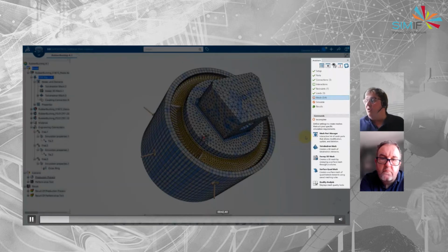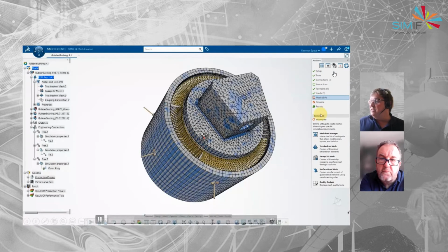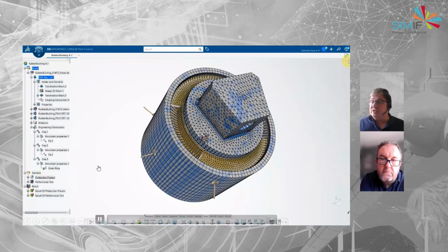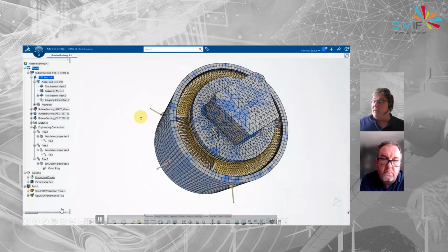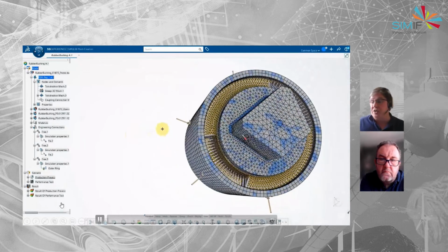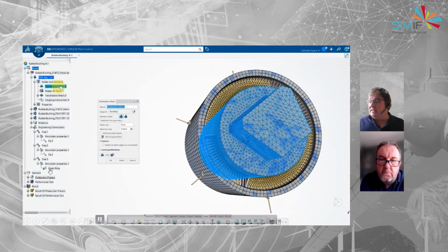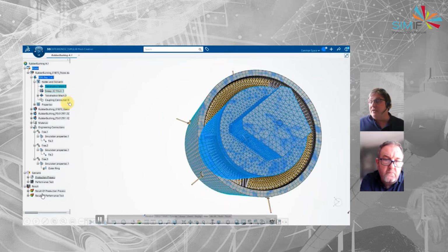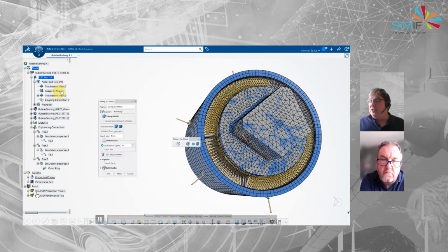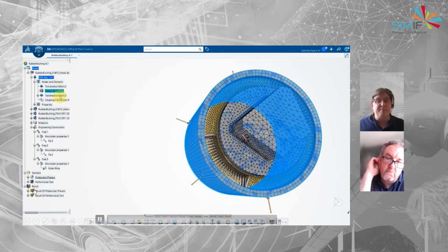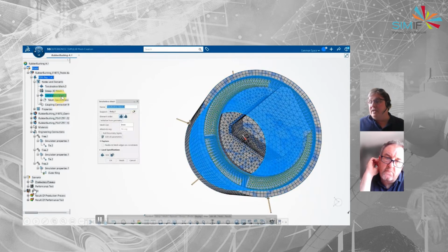We've added a lot of the points in the assistant. So we've got the setup, we've got the parts in, and we've got the connections. But now we're going to just have a look and see all the different types of meshing that we've got. In that central hub, we've used the tetrahedron mesh, and we can see there that we've got a whole host of various options that we can specify for it. For the rubber, for the outside, we've got the swept mesh. Again, really controllable.